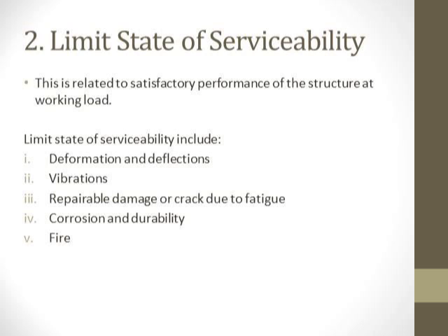The limit state of serviceability includes deformations and deflections, vibrations, and repairable damage or cracks due to fatigue, corrosion, durability, and fire. So these are the points to be included.